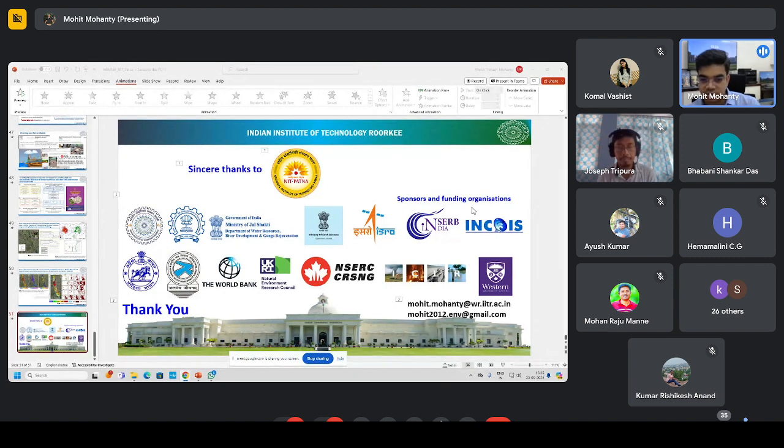Tide is a very usual component. There is a usual tide level for every catchment, every coastal region in India. But because of a cyclonic depression, there might be an increase in the height that is known as storm surge. If you add both of these, that is known as a storm tide. The other component that we do not often talk about, because it will happen maybe after 40 or 100 years, is the sea level rise.